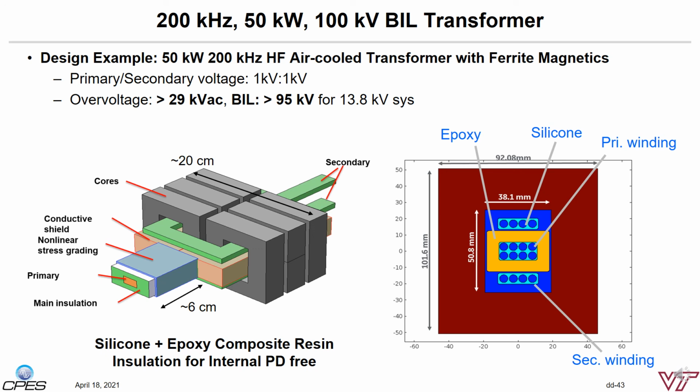The left bottom picture shows the overall electromagnetic and insulation design concept. To minimize the winding losses, the design only considers 4 turns by using this wire bundle. Each turn is constructed by paralleling 2 lead wires. 6 sets of UI ferrite magnetic cores are used to provide the magnetic path. An interleaving winding configuration is applied to reduce the leakage inductance, so the low voltage side windings are split into 2 parallel coils and then are put on 2 sides of the primary windings. The entire primary side windings are insulated by the silicone plus epoxy composite solution.